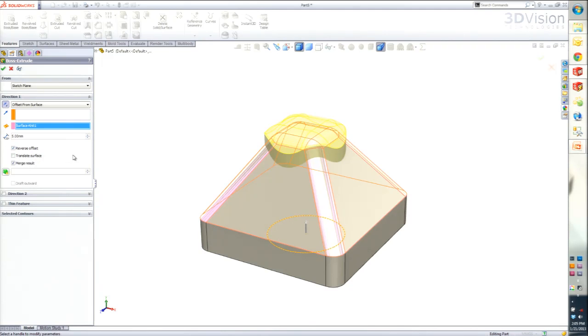Okay, and that's a way that we're referencing the surfaces that were created by the original solid geometry tools, but we created just another sacrificial surface so that we could reference all those faces at once. We're kind of tricking SolidWorks. The nice thing about this, though, is that that knit feature is always based on the solid model's faces. So if they change, the surface will change, the offset from surface end condition will change as well, so that it's always still a very tight relationship to the original geometry.